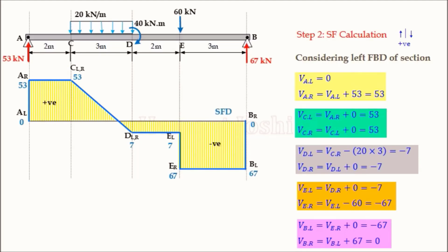Now, according to our properties of shear force, that table what we have seen, we have to check holistically whether my shear force diagram plotting is correct or wrong. First checkpoint is point loads. Observe, this is a point load at A. And as I said, whenever point loads are acting on a beam, the shear force diagram rises and falls. Upward point load, so it is a rise. Downward point load, so it is a fall. Upward point load, so it is a rise.